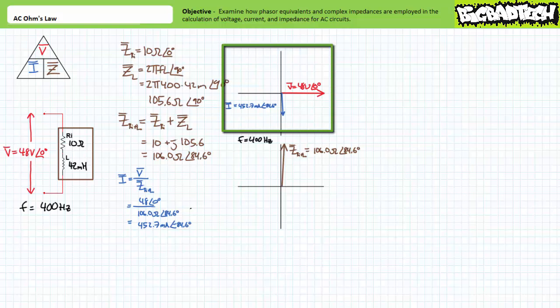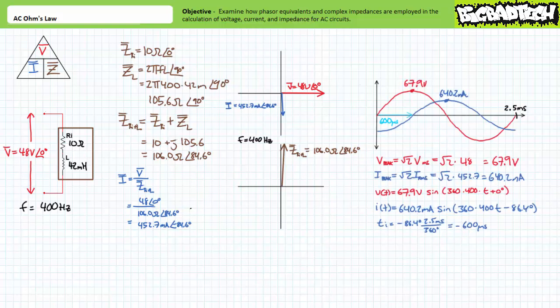Note the Phasor diagram shows I lagging V by 84.6 degrees, super close to what we expect to observe for an ideal inductor. If you wanted to, you could derive the time-variant expression for voltage and current and plot them as a function of time. However, it's kind of unnecessary to do so, given all this additional information is just kind of useless filler compared to that conveniently expressed using the Phasor equivalent diagram.